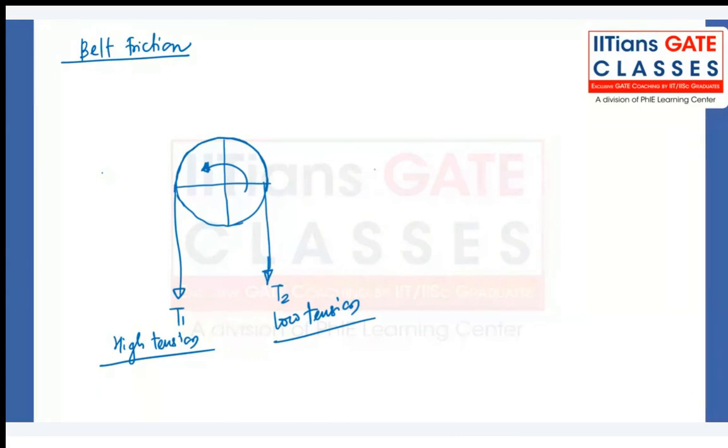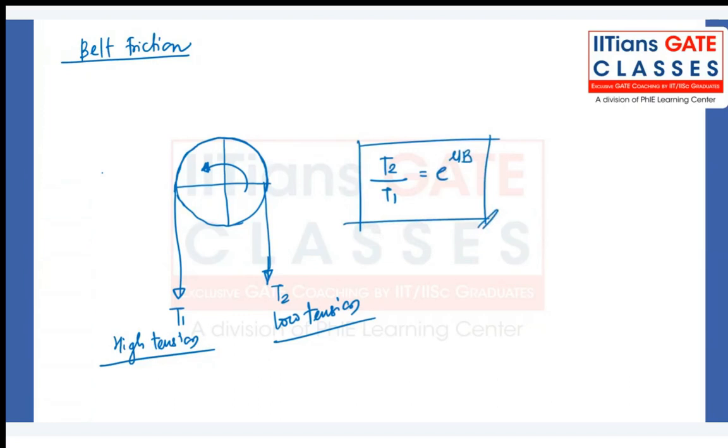That is what I'm trying to explain here: how the ratio of T1 and T2 is related to each other. The tension on the low tension side divided by the tension on the high tension side is equal to e to the power mu times beta, where T2 and T1 you already know. The value of mu is the coefficient of friction between the belt and the pulley, and beta is the angle of contact.